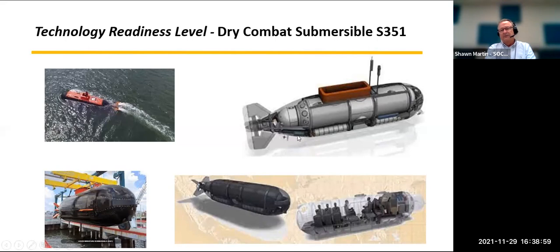So right there are the battery bottles, ring stiffened cylinder. And you've got some O2 flasks here, but the pressure hull, I'm trying to give you an idea where it's at, all this, and that's the lock in and out chamber. That's a hatchway right through there. That's where divers lock in and out, and our seals. That's all well understood: design, materials, fabrication, process, very, very well understood.